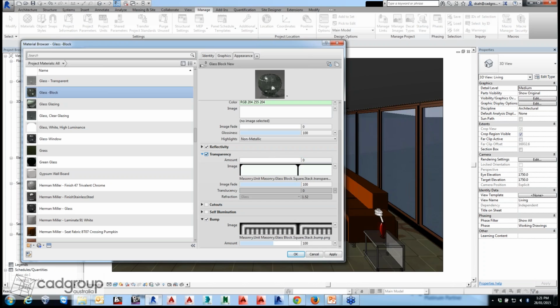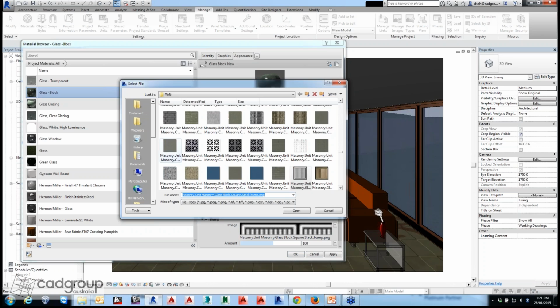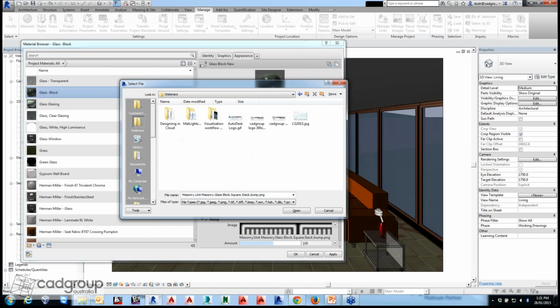If I look at some of the parameters, there are a couple I'd like to change. In this particular example, in the rendering, I removed the transparency because they used a couple of different materials there, with bumpiness and transparency. I'll just remove the image, use a little bit of transparency, add an amount, let's say bump to maybe around 75, and use a bump map.